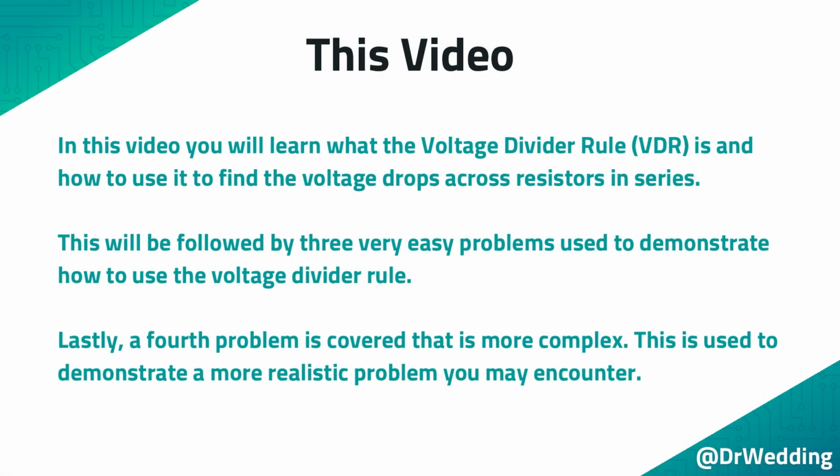In this video you will learn what the voltage divider rule is, and how to use it to find the voltage drops across resistors in series. This will be followed by 3 very easy problems used to demonstrate how to use the voltage divider rule. Lastly, a 4th problem is covered that is more complex. This is used to demonstrate a more realistic problem you may encounter.